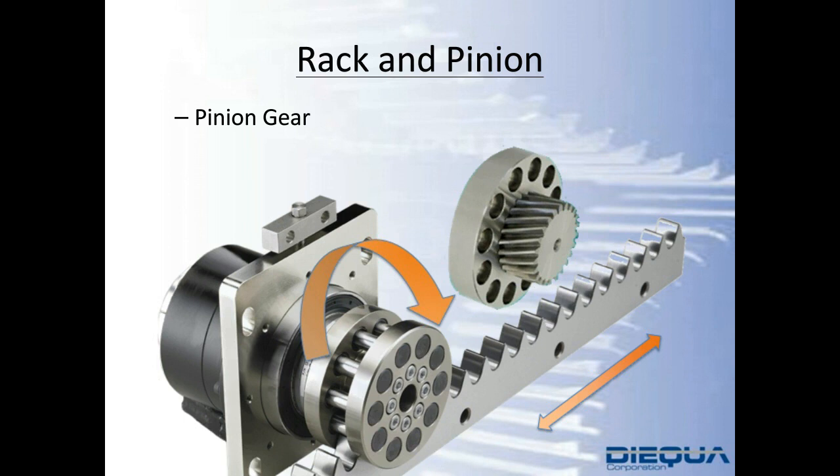On the left, you'll see the roller type, and on the right, you'll see the helical cut gear. A third one you might be familiar with is a straight cut pinion gear. The benefit between the three is how they influence reactionary forces induced onto the face of the gear reducer. And so that's the critical thing here.